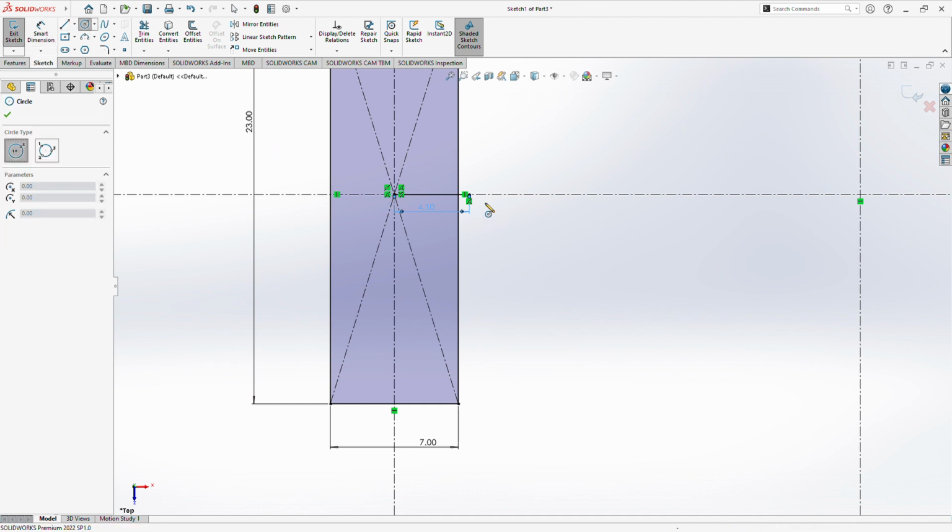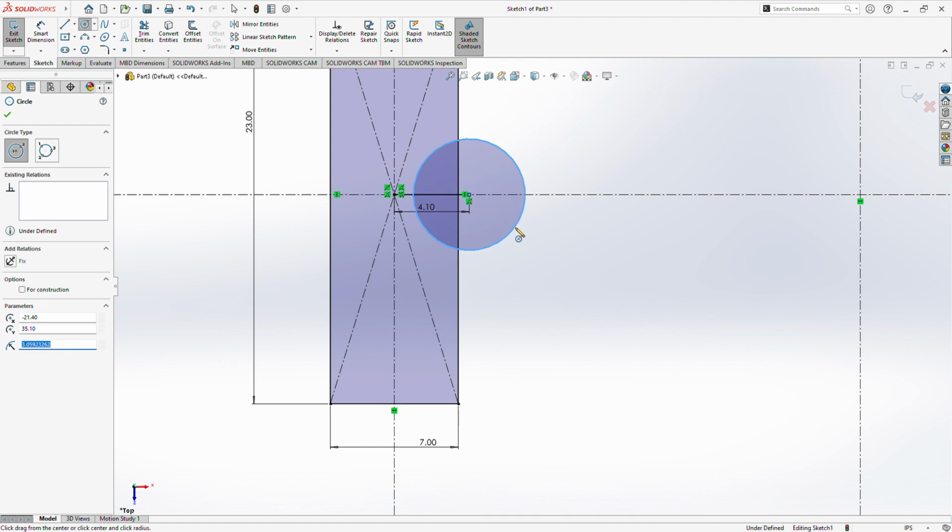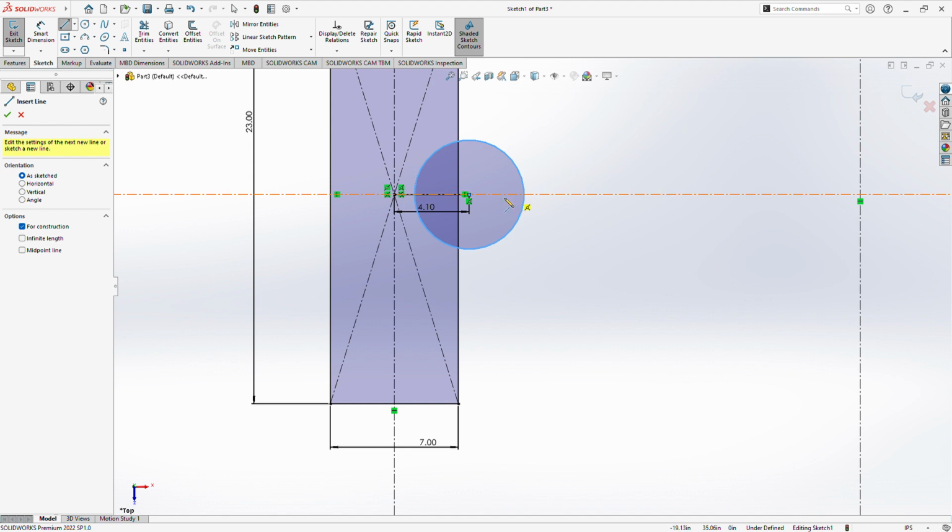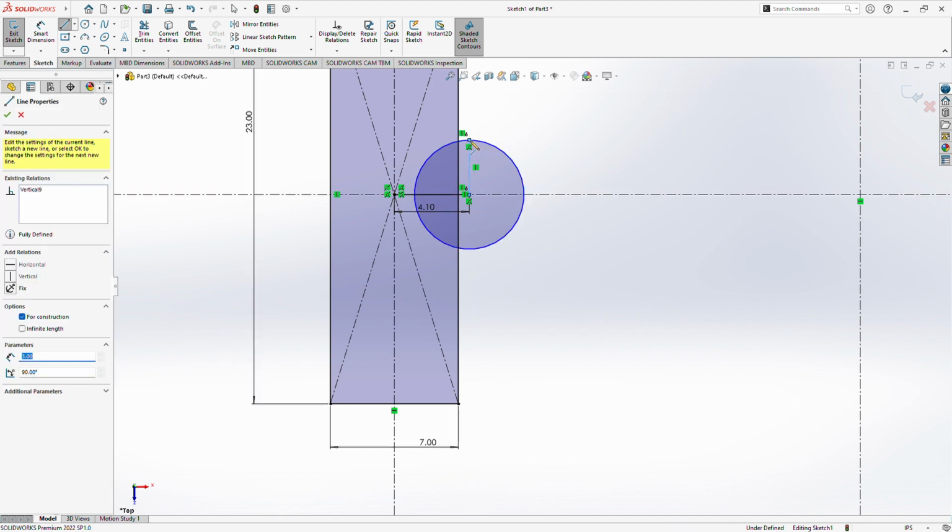Make a circle representing the locus of the steering arm. The steering arm length is 3. That is the radius of the circle. The steering arm will be attached to this point and it will move on the locus of this circle. We'll take its radius as 3 inches and the length of the steering arm is 3 inches. Okay. Mark a center line representing the vertical from here.